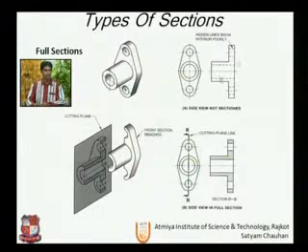If we are drawing a conventional front view, it will come with the 1, 2 and 3 holes represented. So there will be 3 hidden lines, one for this circle, second for the middle circle, and third one for the bottom circle. The side view is not sectioned. This is the full view of this.